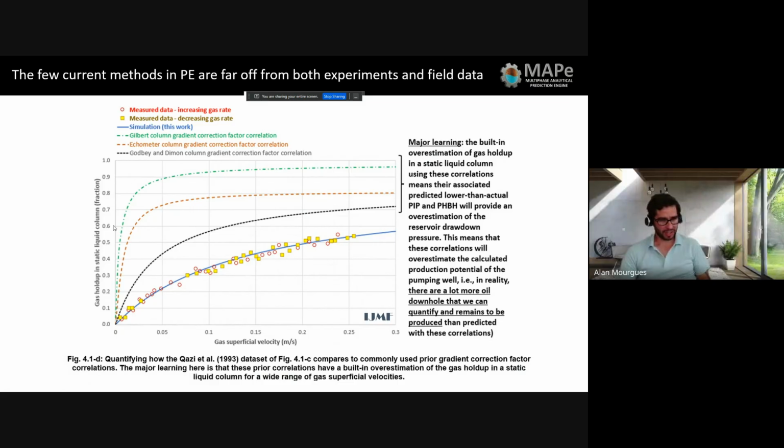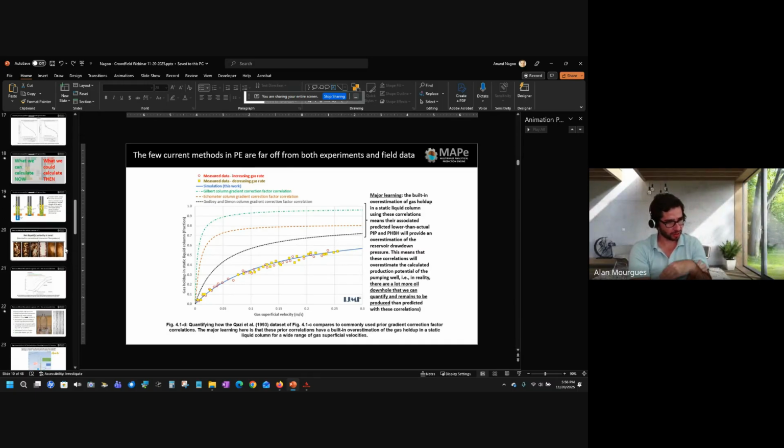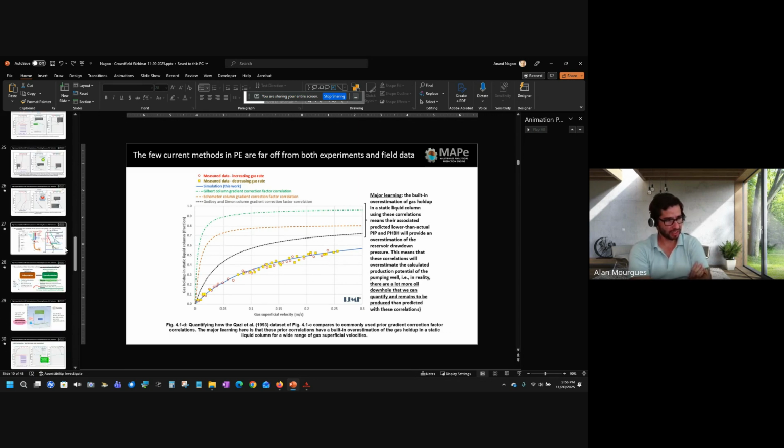It does for sure. Anand, I have a question myself. If I understood correctly, and correct me please, the great breakthrough here is not only that, unlike the conventional understanding where a dominant flow regime applies, you're saying there's a bunch of flow regimes happening all at once, and therefore you're coming up with an alternative path to compute pressure losses along the well on account of those many flow regimes coexisting, which also includes these large-scale recirculations, which add additional pressure losses which were not accounted for before in any of the conventional methods. That's what I'm seeing as the breakthrough here. Am I right or wrong in understanding that?